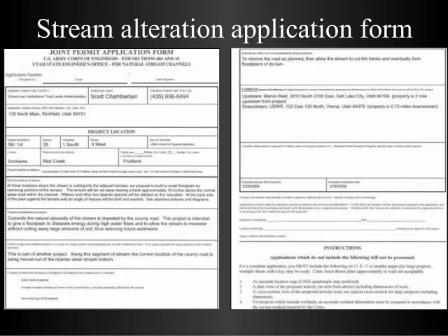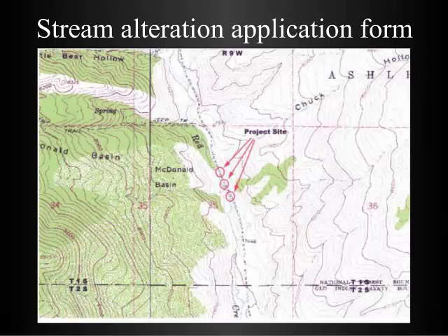It talks about what's going to occur for the project and who the adjacent landowners are that may be impacted. This shows on a topo map the sites where the slopes were going to be, along the old road. The new road came off this corner and came out just off the floodplain and then curved back around into here. At three of these sites where the road had been undercut by the stream, we proposed to lay back the slopes and revegetate those.